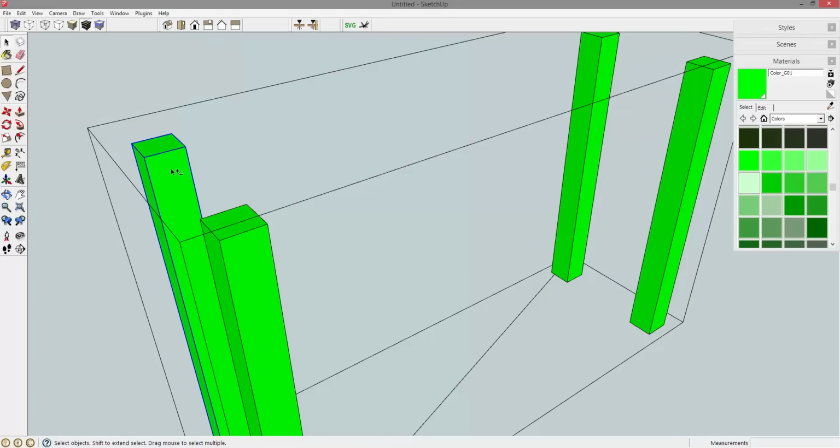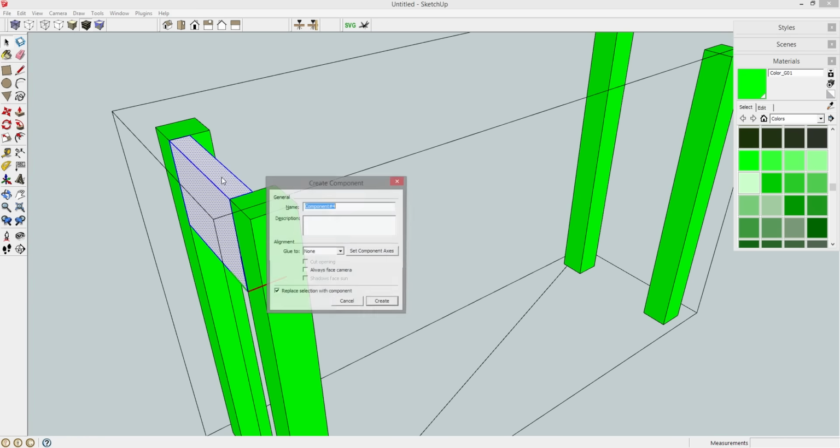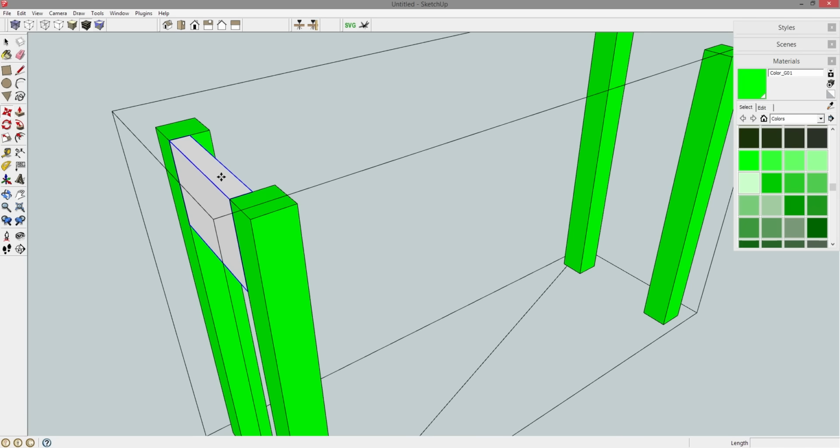So on this leg, let's press R for rectangle and drop a rectangle, and I know that my first dimension is the shorter of the two, so the thickness is 1.25, 6 for the length. That's the size of my rail. P for push pull. Let's pull it to the inside of this leg over here. Spacebar, triple click, G for component, enter, M for move, and I want it to be inset by 0.25 inches